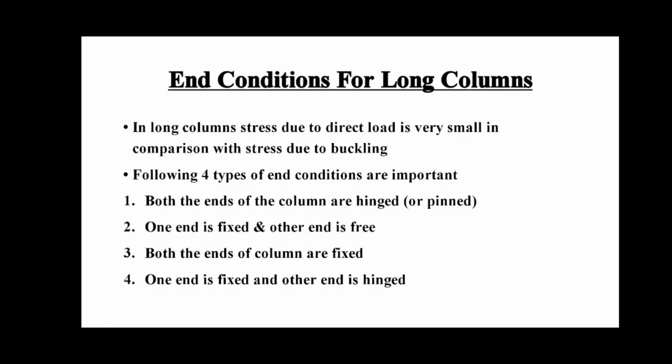Next is the end conditions for long columns. In case of long columns, the stress due to direct load is very small in comparison with the stress due to buckling. Hence, the failure of a long column takes place entirely due to the buckling or bending that we have already told.